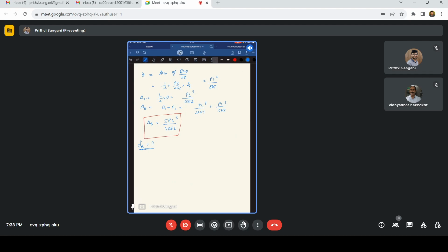And when it comes to internal indeterminacy, what happens is that, let me take one member here. I'll take this joint H. Let me draw it here. When I cut this section here, here, and here, what are my internal forces which are going to generate? You have shear force, bending moment, and axial force. Again you have axial force, shear force, and bending moment here. You'll have shear force, axial force, and bending moment.